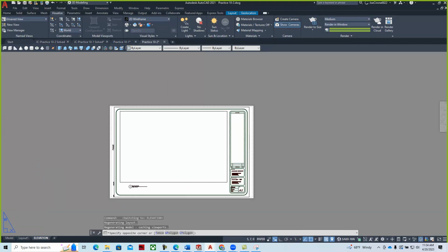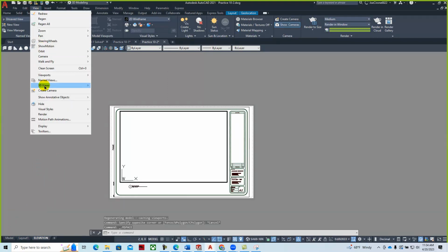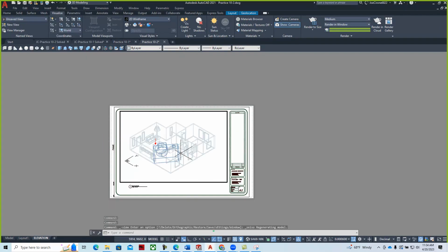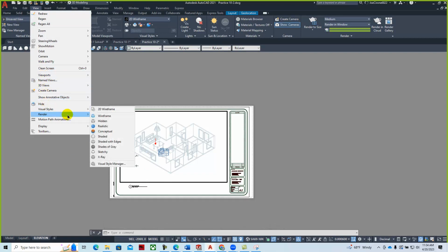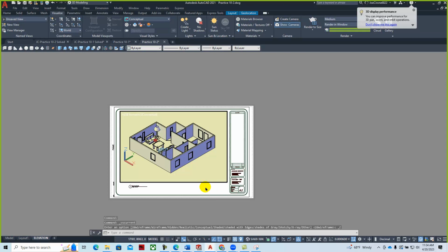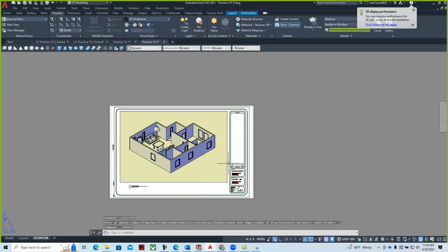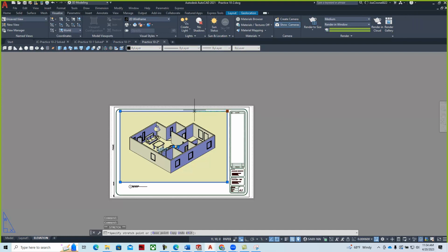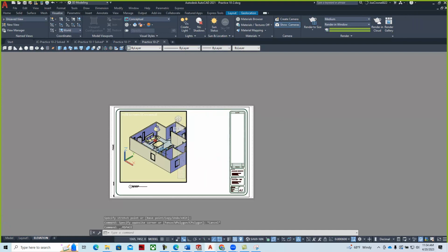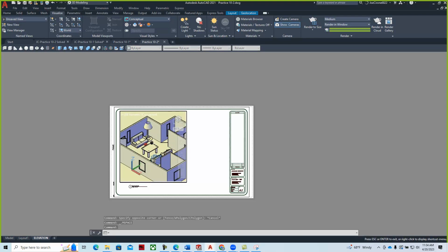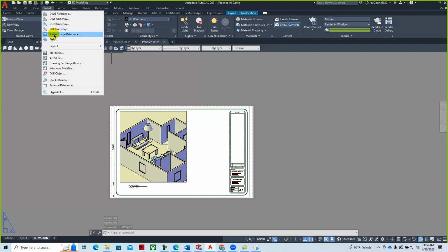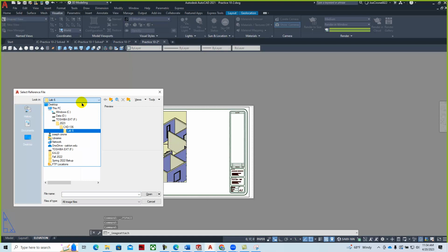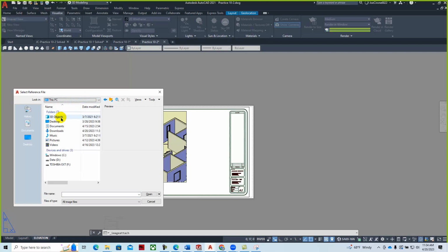Here's our elevation. Double click in the view. 3D view, southeast isometric. Zoom in on that. Let's render that. I'm going to go with the conceptual, and then we can double click out of that depending on how big you want to make this viewport. Let's go and bring this over like that. You can click outside of here, insert raster image reference from my downloads. Here's my house.